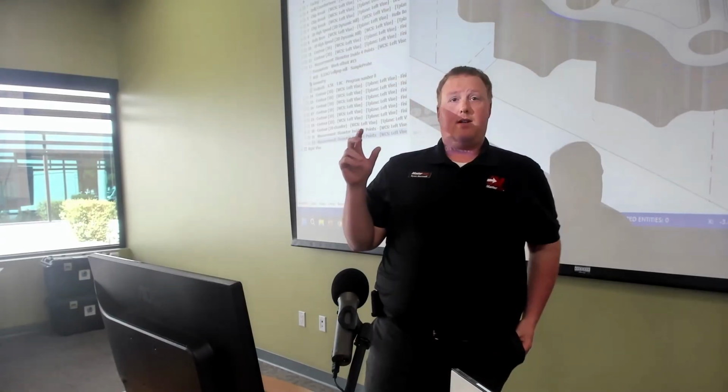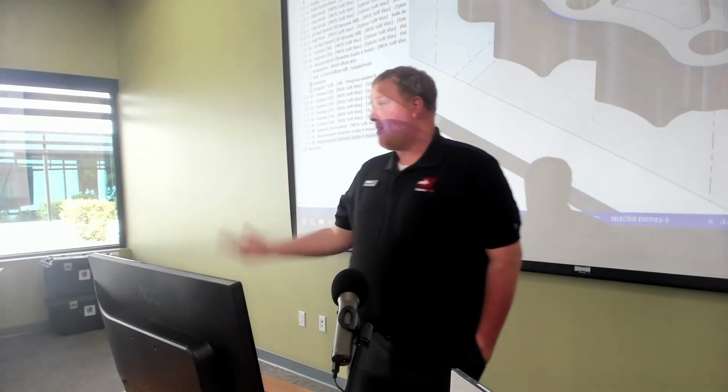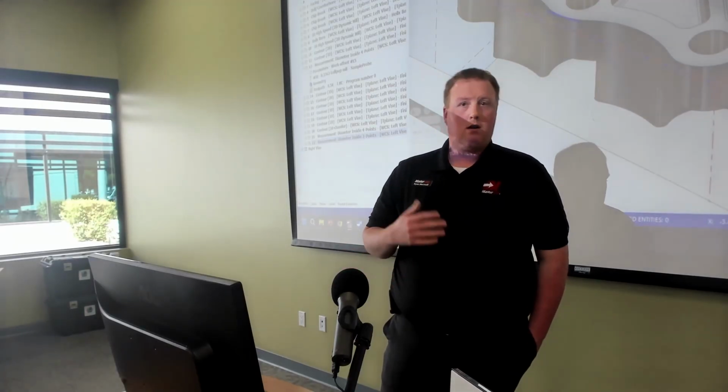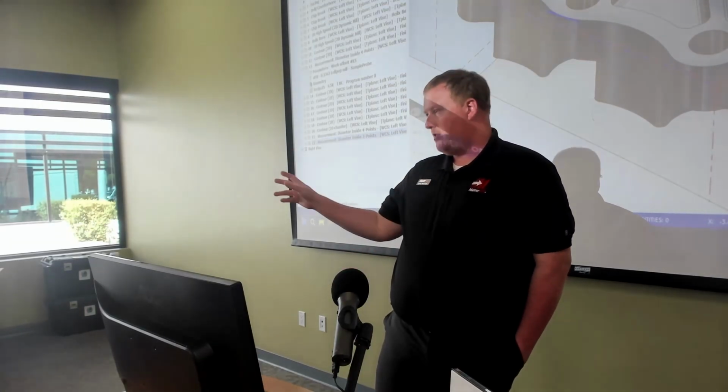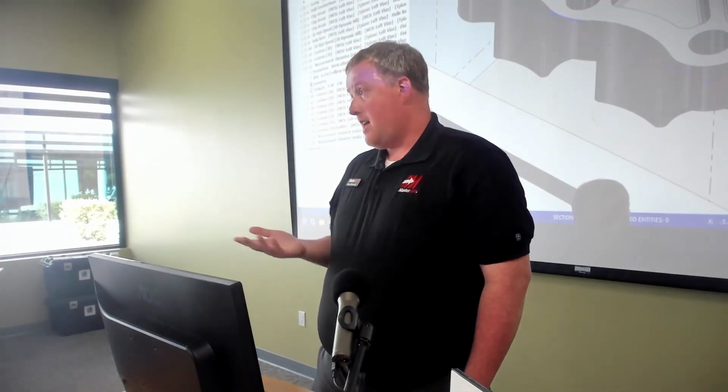So whether it's a Renishaw on an Okuma control, a Haas, a Fanuc, right, Matsuura with their PQI macros. So that's where we define those different portions as part of it. So I would say the best bet would be just reaching out if needed and sending them a zip to go on that. And also the mill default post in 2026 does contain that logic already.